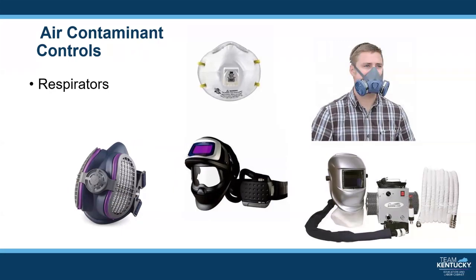When other methods previously mentioned are not effective or not feasible, respirators could be provided and used by the employees when needed. This can be found under 29 CFR 1910.134. Respirators are generally somewhat bulky with the half-face mask and the filtering cartridges attached. See the picture on the top right. This type of respirator would not be compatible under a welding helmet.